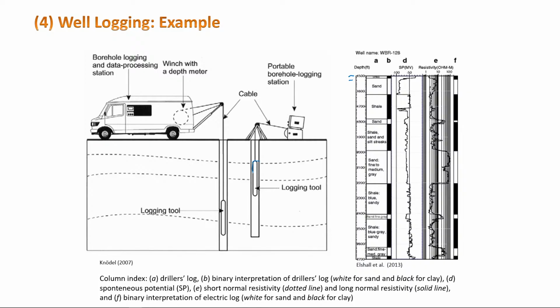you have your logger, you drop it in, you do your reading, and then, as it has a cable, you keep dragging it down, down, down. As it moves down, it takes a measurement. And it could take a lot of measurements. It could not only do resistivity, it could do self potential. And you know what else it does? It does borehole camera. Borehole camera is just a camera for the borehole, and it's a 360-degree camera.